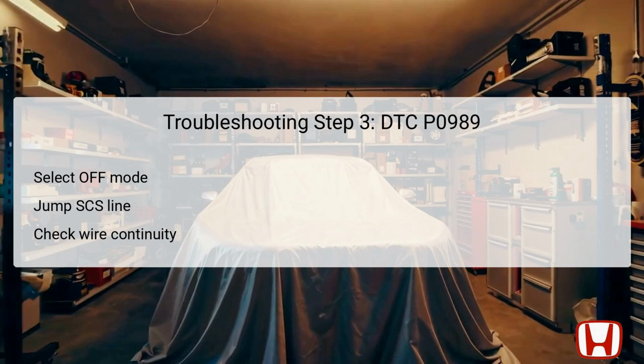With both the switch connector and PCM disconnected, you can check for continuity on the OP6SW wire, which is responsible for transmitting the signal between the switch and the PCM. Identify the test points properly. Test point 1 is located at the PCM connector, B51P, number 28, and test point 2 refers to the body ground. A continuity test will reveal whether the OP6SW wire is shorted to body ground. If there is continuity, this indicates a failure in the wiring that should be repaired. Otherwise, if the wire checks out, the PCM may need replacement.